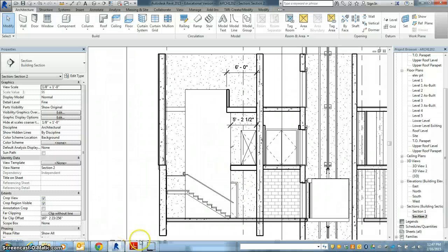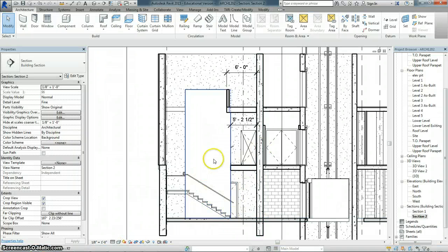So let's go to the Revit model. You can see here I've built the center wall. I have my landings. I've got my top landing at 6 feet, and my main level landing at 5 feet 2.5 inches. You also see that I've located the lower level stair, so there again I have the wood stair built and then just the guardrail. Now I put them on both sides, even though the drawing actually only shows it on one, but I've got them shown for code reasons on both sides. So let's look at putting this stair in.